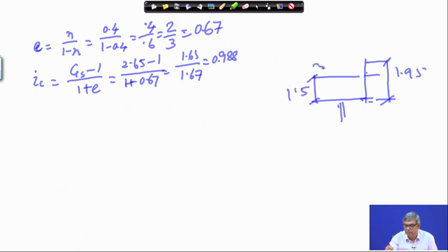Okay, so the requirement is how much sand to be put here, because since this height is more, the critical hydraulic gradient will be something, and because of this height, when you allow flow through this, the sand may wash away. So because of that you have to put additional weight to balance it, and that too you have to provide a factor of safety of 2.5. So with that consideration, we can consider clay to be used. Since flow is passing through this, there is no water table,